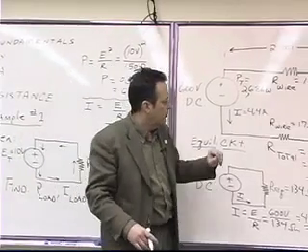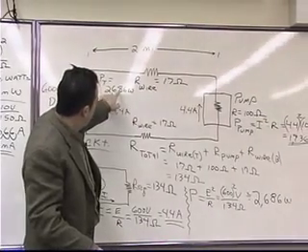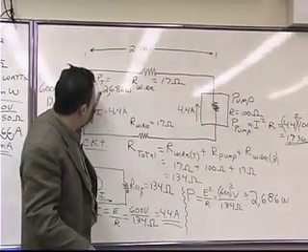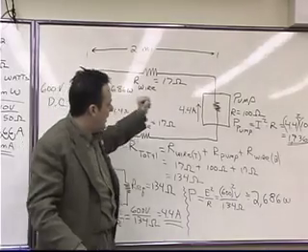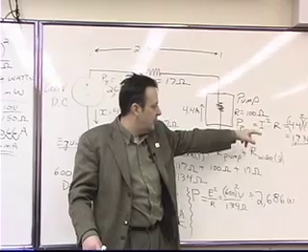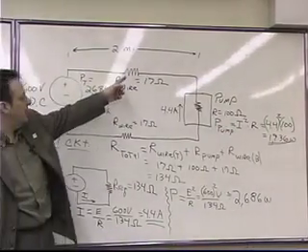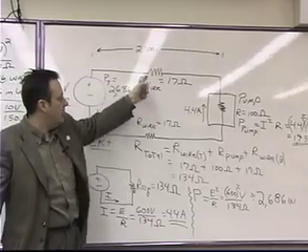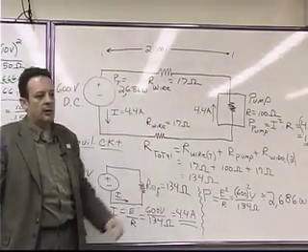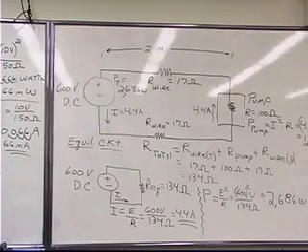Okay? So, if we have 2,686 watts that we're generating, and our water pump is eating up 1936 watts, then how many watts is being dissipated in our forward and our return wire? 750 or 375 each.